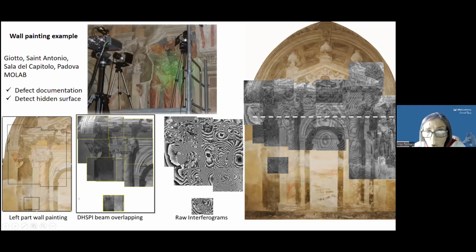I want you to notice here that the interferograms might look complicated, but they are not. We have a whole body reaction, so how the structure as a whole reacts to the induced displacement, whereas we see many localized discontinuities, which give us the information about the subsurface defects, and we can study these discontinuities one by one.